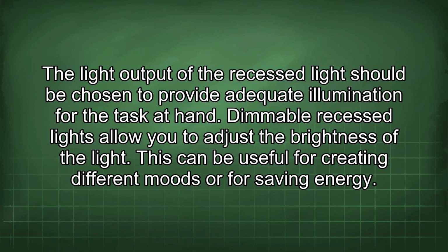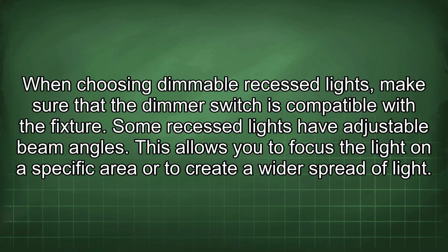Dimmable recessed lights allow you to adjust the brightness of the lights. This can be useful for creating different moods or for saving energy. When choosing dimmable recessed lights, make sure that the dimmer switch is compatible with the fixture.